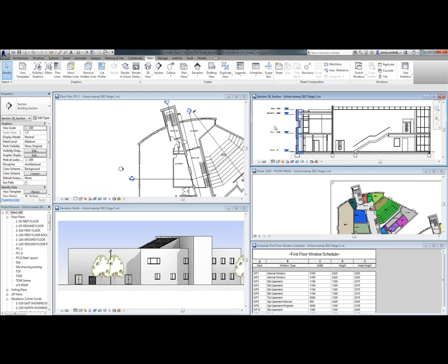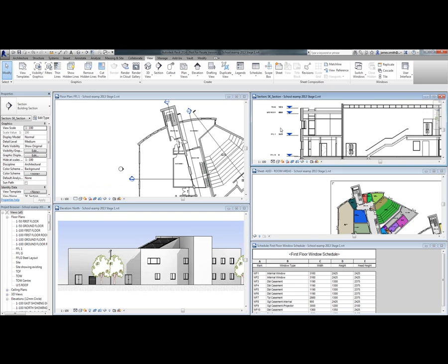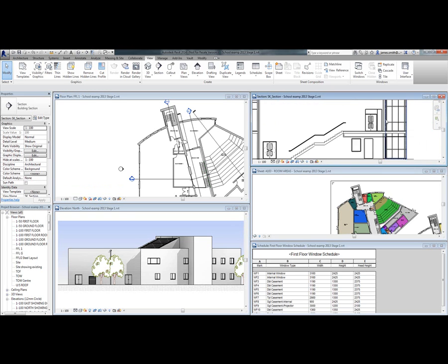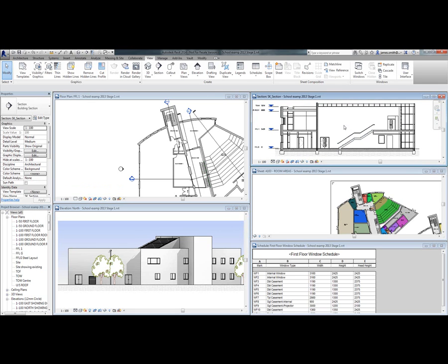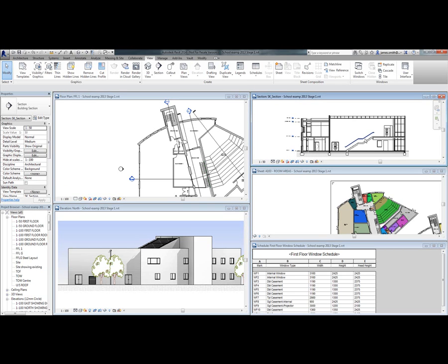We've also got our section views. So you can see here I can zoom in and have a look at any particular area. If I were to update this view, it would also update all of the other views where it's relevant. You can set these scales. This could be set as a particular scale. So if you are creating drawings, you can drag and drop these elevations.